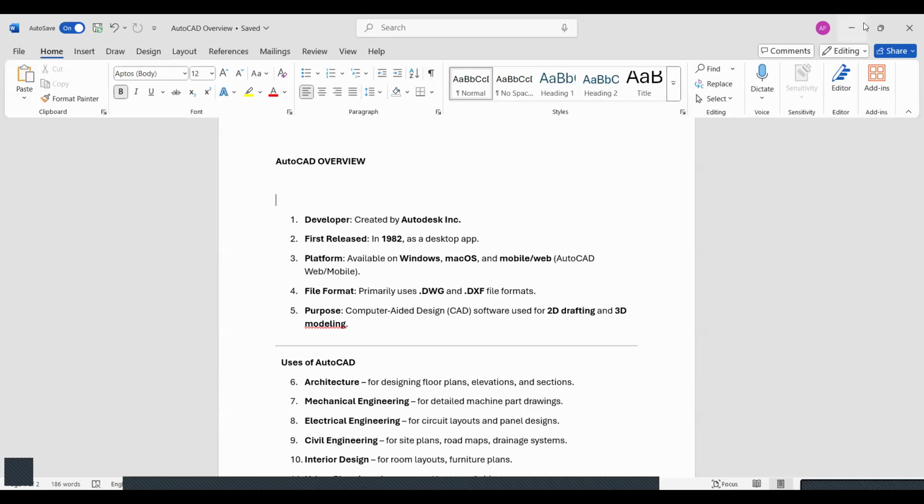if I'm deleting each and every part and I'm applying this thing, only red color, and I'm selecting the entire drawing, then only red color part will be highlighted, because in the filter command what I have used, the object will be circle and I'm discriminating it with the colors. So by discriminating it by the colors, the red color got selected. Then I can do this.